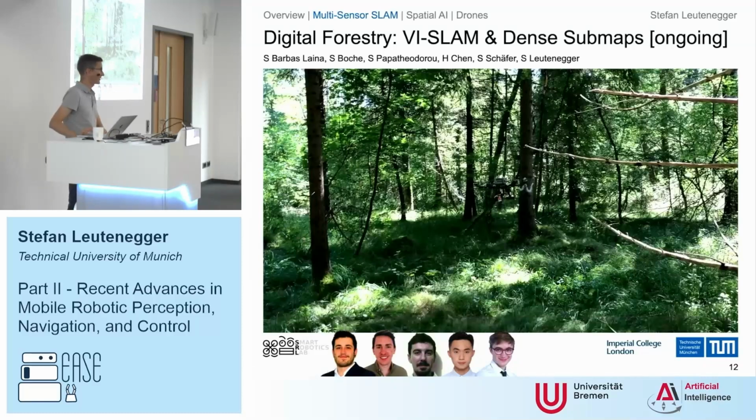Any more questions? Yeah, so one thing I could notice is all these trees are of course static, but if there's an environment where there's swaying of leaves which are nearby, is there any experience you could share where you had flown your drone where there are dynamic obstacles, which are not so static trees? This is a good point. I didn't really talk about it, but this is of course one of the big challenges that we are facing, and we have actually seen that, for instance, you take off, you're blowing around leaves, and it kind of messes up your map because you have all of these leaves in there that are moving around. Or you then don't see the stuff that actually is there because it's just been moved in front of the drone.